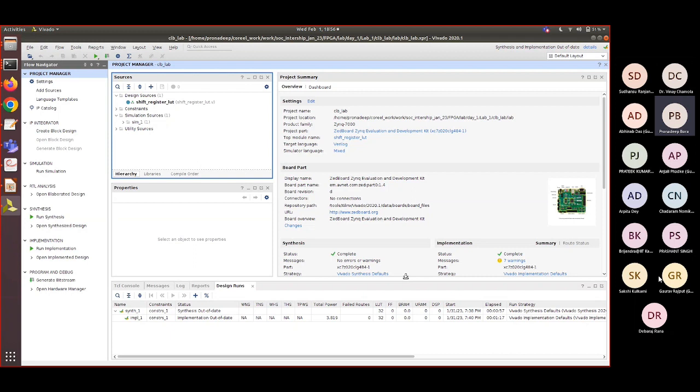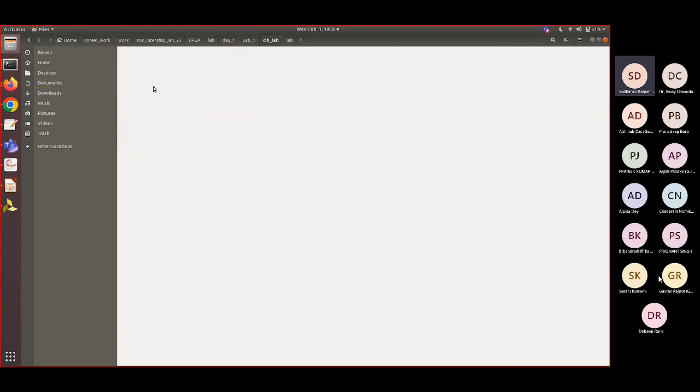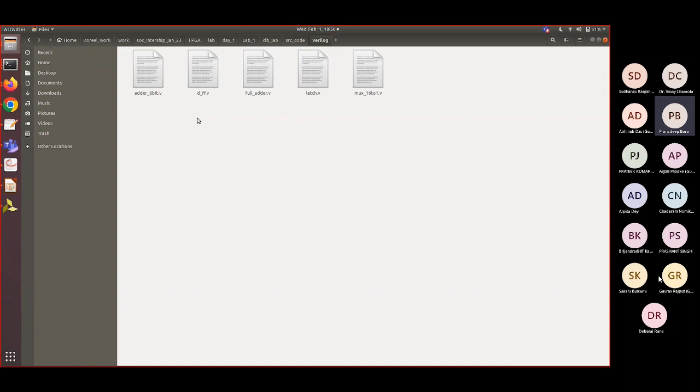If we make it PIPO, then again it will increase resources, because in parallel, for 1 bit it will have only 1 bit shift, whereas in serial in, serial out, you can use shift register logic in LUTs so that 1 bit can have a 32-bit shift. So again, the implementation and the utilization will go high.